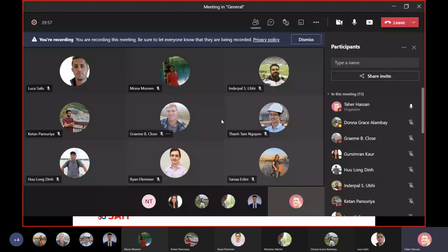You can get a digital surface model. When I say digital surface model, it's 3D, same as the face, like the mask that I processed last class. So you can get a full 3D model, or you can get an orthophoto. An orthophoto just rectifies your image, which means it removes all relief displacement. An orthophoto is a two-dimensional product, which means showing you the right location of the object. So you can get both products: an orthophoto, with no elevation, or a full textured 3D model.